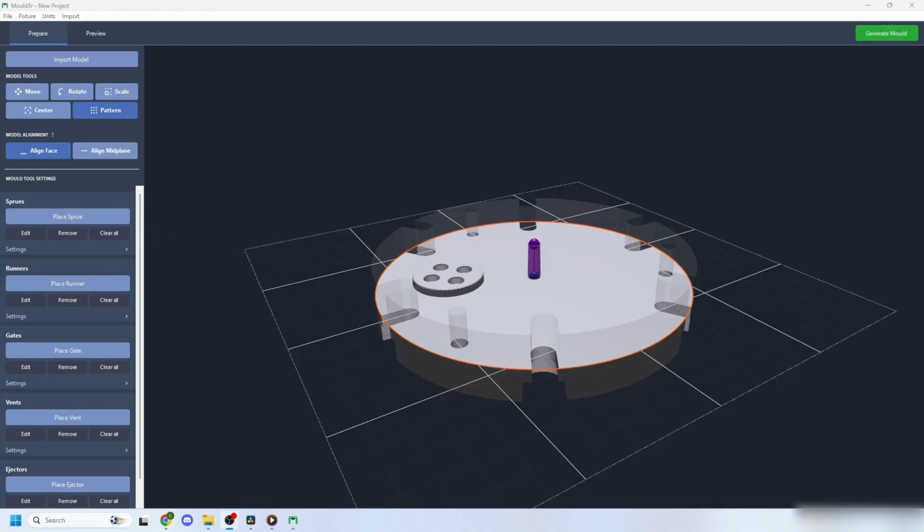For more complicated designs or multi-cavity molds, we continue to runners. Runners let plastic flow through the mold, distributing it to different sections. And note, the sprue must have a contact point for runners to be calculated from. If you're trying to place a runner and nothing shows up, make sure there's a dot indicating where the sprue contacts the parting plane. If that's missing, try generating the sprue again.